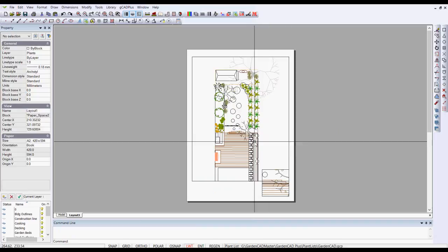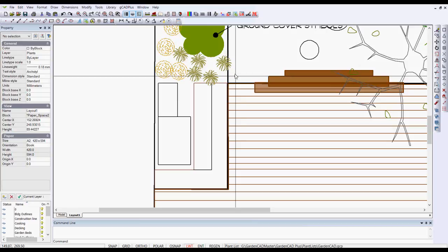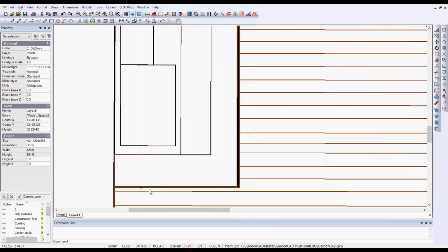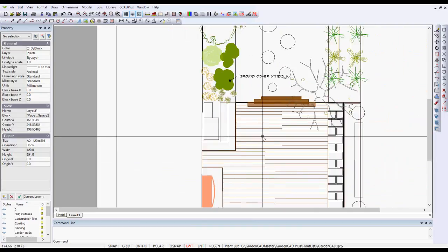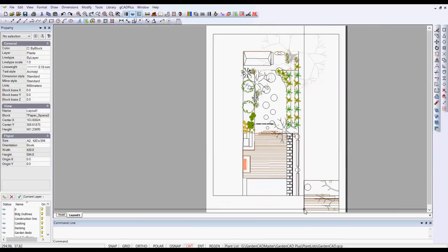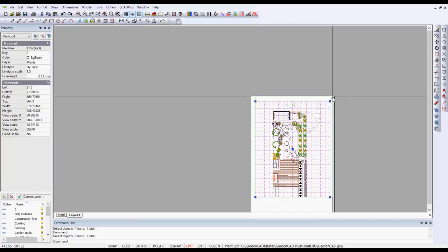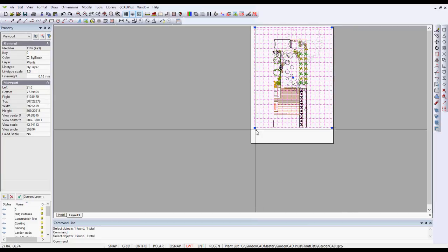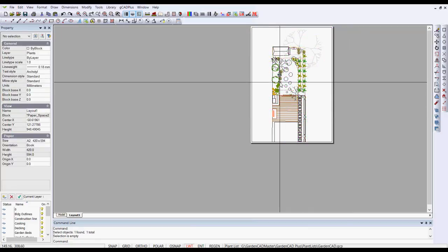Now deactivate that viewport, and now when we move in, you can see the thick lines appearing. I think there's a bit of poor drafting there, but we'll deal with that in a little while. So can you see that the lines are set implicitly? As I said, that works fine. There's another little layer here which I think we can remove, and that will enable us to stretch the floating viewport out so that it occupies the whole of the page space.